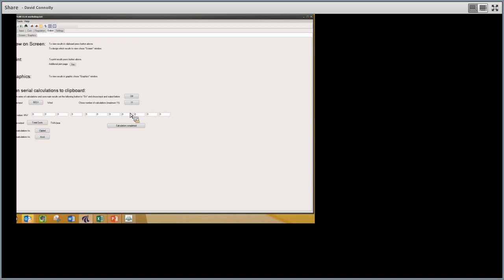And what this serial calculations does is it allows you to input a variety of different numbers for EnergyPLAN to change one single input and run the results in a series of calculations and give you the results for a variety of different inputs. So for example, if I turn this feature on using this button here on the right, now the series calculator is on, which means that when I press this preview results screen, I'll no longer see the results for just one scenario. I'll now see the results for all of the scenarios in this sheet here.